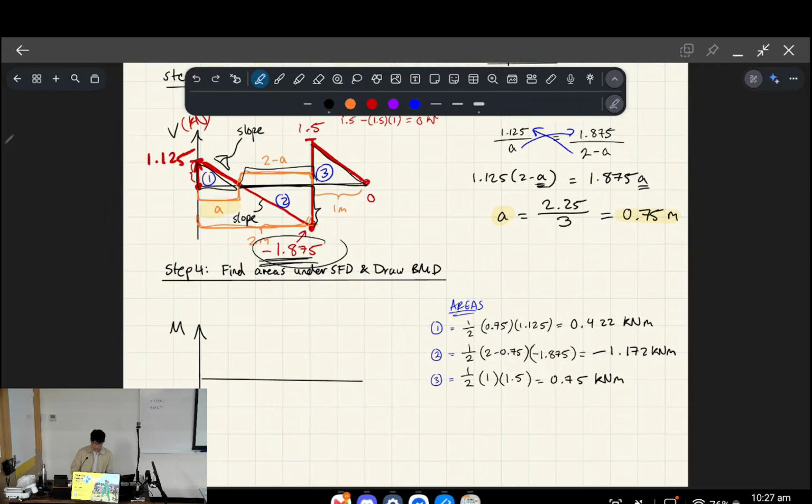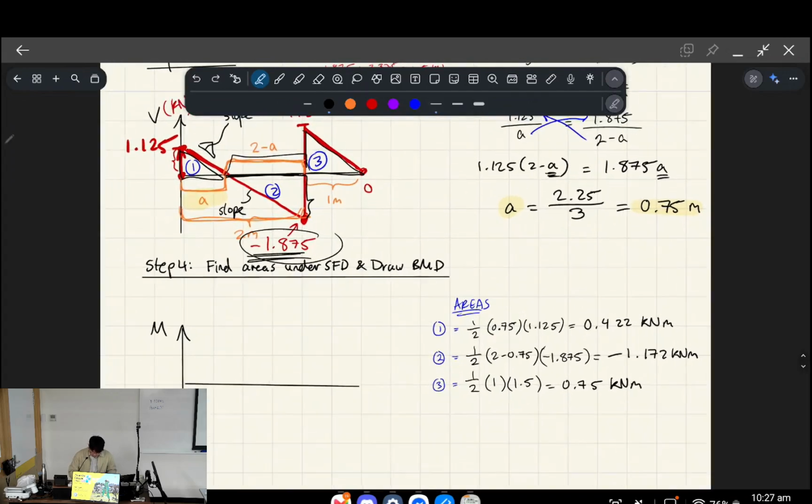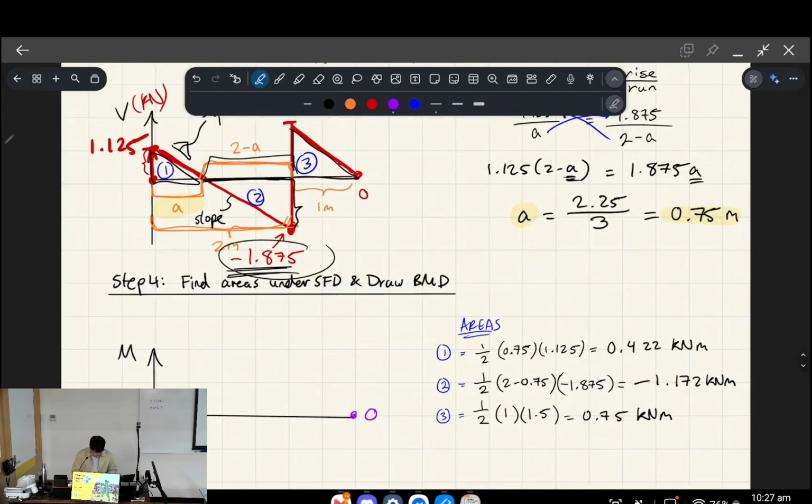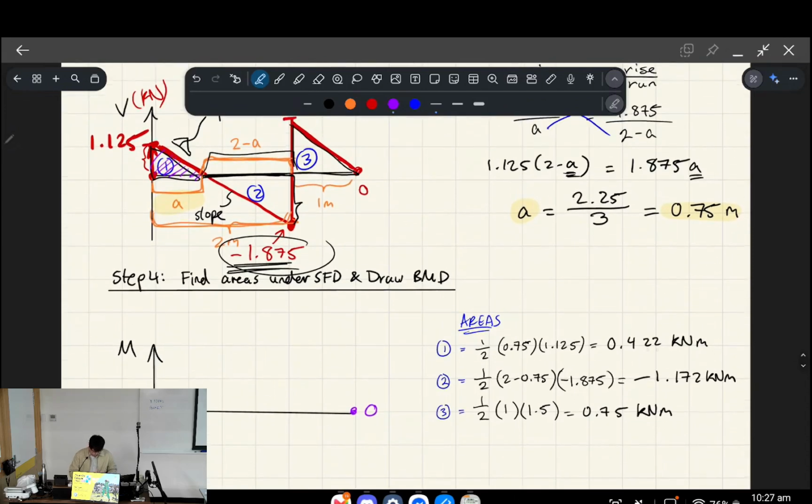So this will be a little bit harder to wrap your head around, but we have a few bits of information which we have to piece together in order to get everything to work. Okay, so the first thing we know is the bending moment will start and end at 0, okay? So that's beneficial to us. The next thing we know is that after the man walks on these triangles, at this x location, we have 0.422 because that's after area 1 has been consumed, okay?